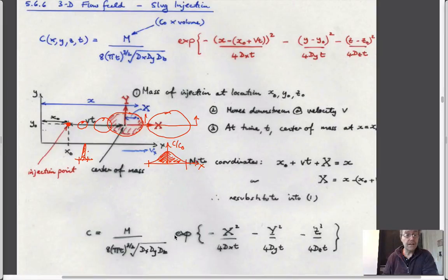It's basically calculated by assuming that you take a coordinate system that you attach to the average velocity of a particle that's going from here downstream. So in a given length of time, the center of mass of this material that you've put in here, the mass of which was this amount initially, it looks like it's more, but it's actually not more. It's more spread out and less tall. You can think that the area under this curve, which really represents the total mass, would be the same. Really tall and skinny, but not so tall and quite broad.